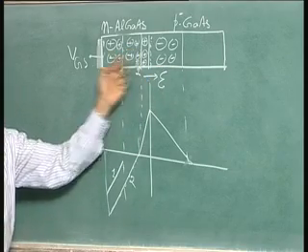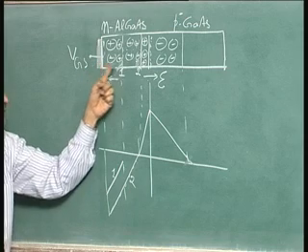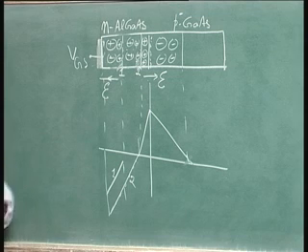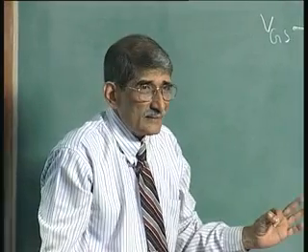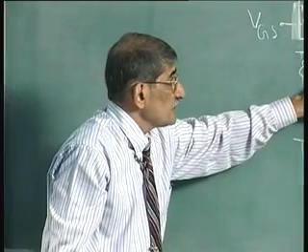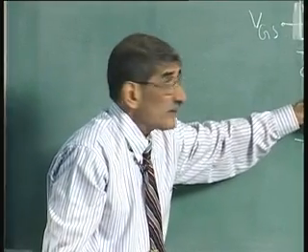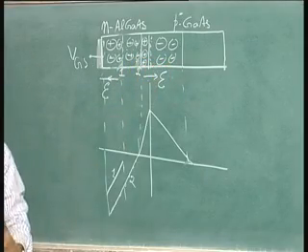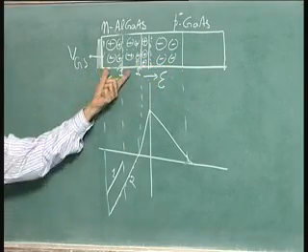All that was happening was that for the minus charge that you put here, plus charge was coming from here. Now, what will happen if I increase this voltage negatively further? See, at this point you have not disturbed the p-n junction conditions, because the interaction was between the aluminum gate and this n plus layer.